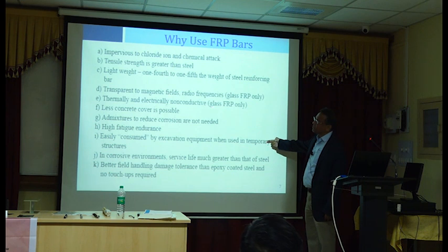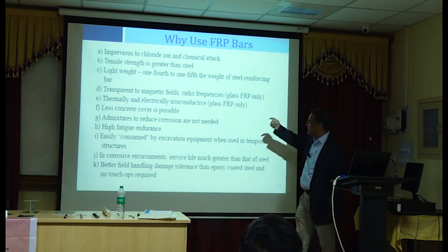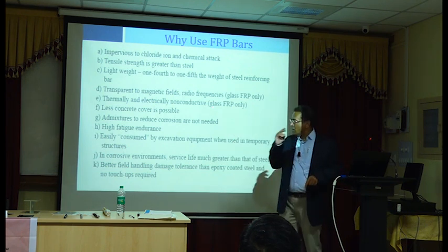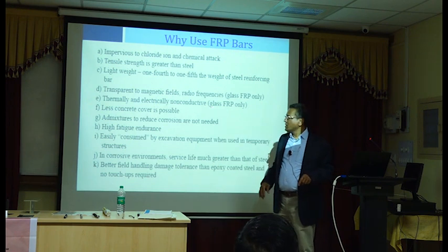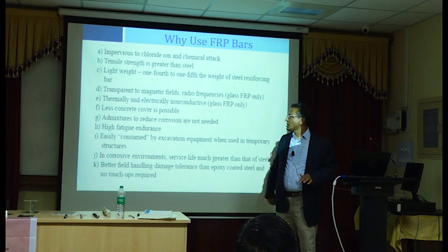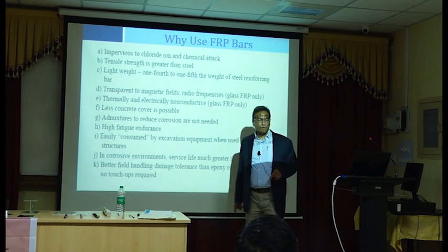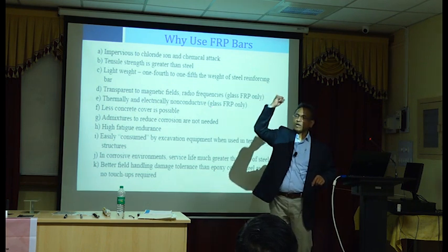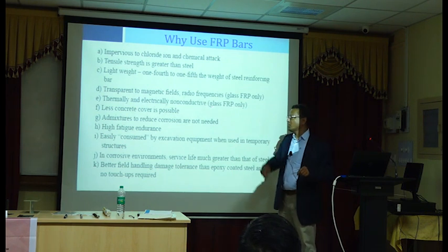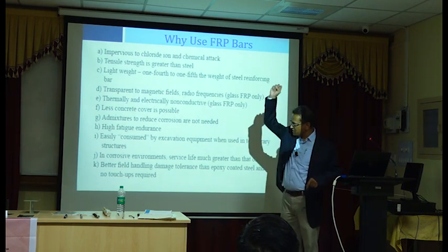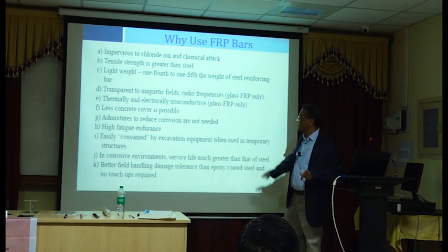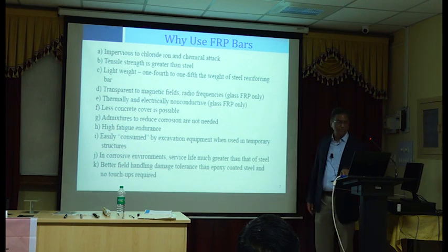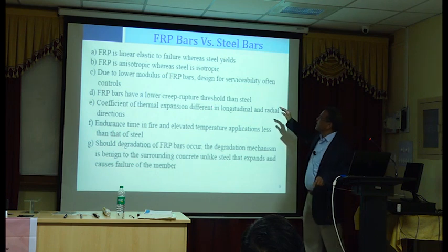This item is new. It says easily consumed by excavation equipment. If you are demolishing anything, you are removing some stuff. If you have already built it and you want to remove the slab, it's easy to just crush the concrete and the reinforcement without any problem, if it is FRP. If it is steel, then you have to use your hammer and then break it. Not manually, but they have these balls, they just drop it and break it. Okay, but anyway, that's another new item. Everything else we covered.